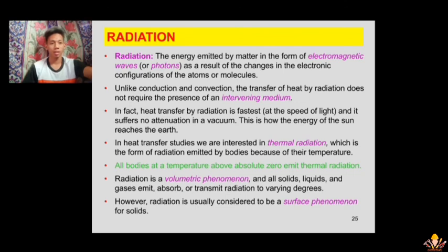Radiation. Radiation is the energy emitted by matter in the form of electromagnetic waves or photons as a result of the changes in the electronic configurations of the atoms or molecules. In heat transfer studies, we are interested in thermal radiation, which is the form of radiation emitted by bodies because of their temperature. Radiation is a volumetric phenomenon, and all solids, liquids, and gases emit, absorb, or transmit radiation to varying degrees. However, radiation is usually considered to be a surface phenomenon for solids.